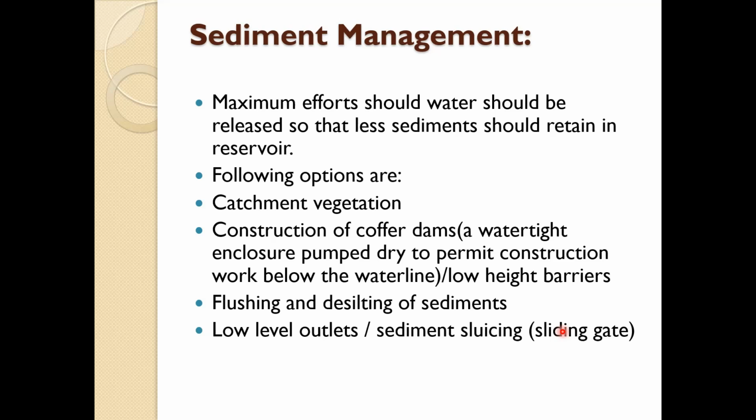Then construction of the dam in stages. The design capacity plays an important role in the silting of the reservoir. When the storage capacity is much less than the average runoff entering the reservoir, a large amount of water gets out of the reservoir, thereby reducing the silting rate as compared to what it would be if the entire water were retained or stored.